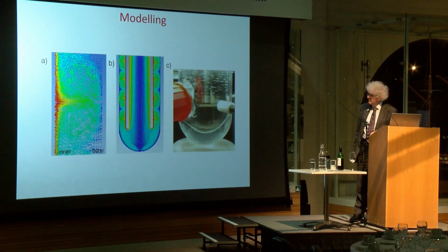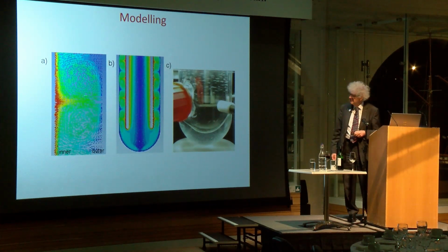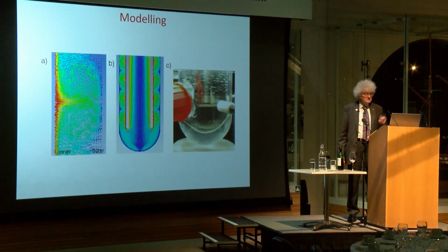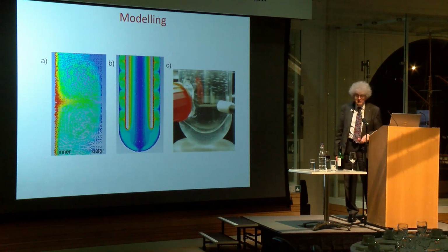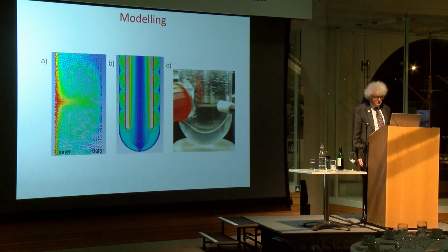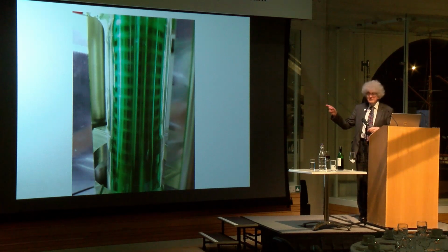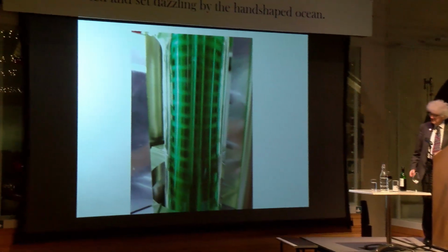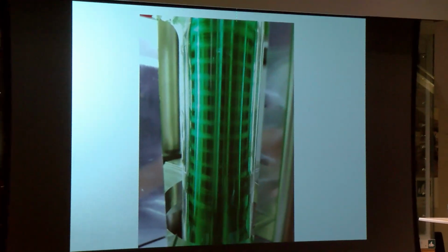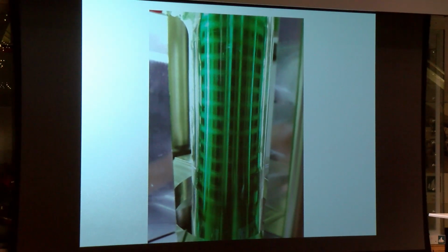And with our engineers at Nottingham, we've done CFD modeling, and you can see here's the modeling of the reactor, and this is the actual reactor where you can see the streams of bubbles. And this is not a simulation, this is a reactor actually running, and you can see these vortices, rather like rings, threaded onto the stirrer.